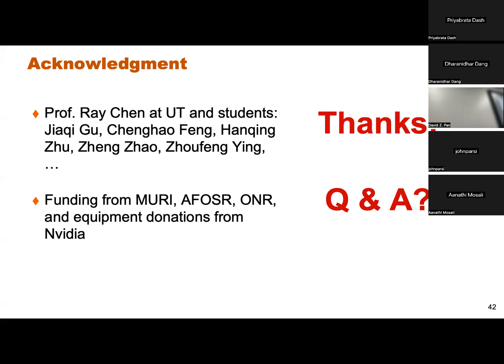I have one last question. When you're doing the matrix multiplication, do you have to put in only one single frequency? No, that's a nice thing. You can have multiple wavelengths, WDM, wavelength division multiplexing. When they all come in, if you are talking about the intensity, you can just get all of them. Then naturally, when you have multiplication, you also have accumulation. They can accumulate.